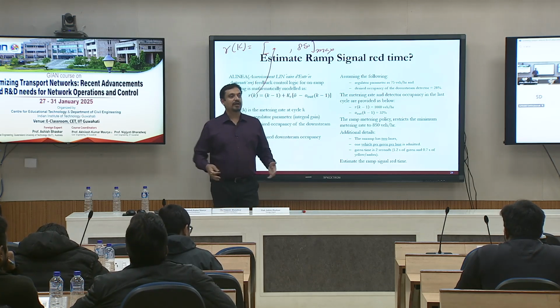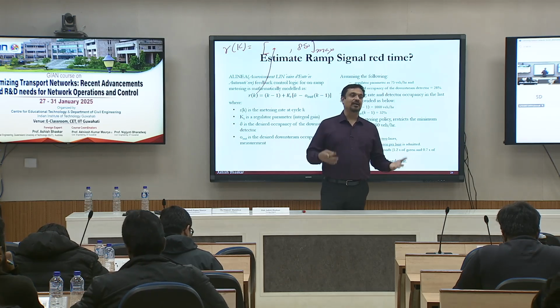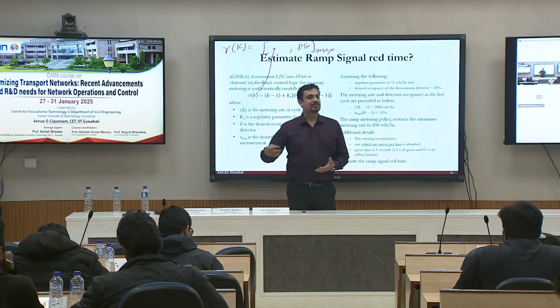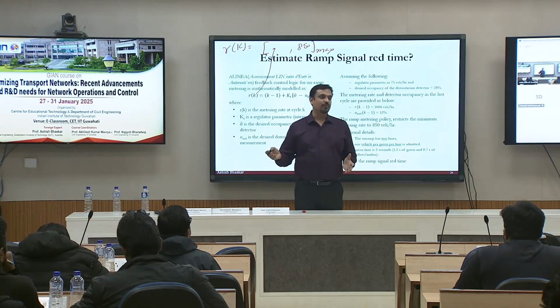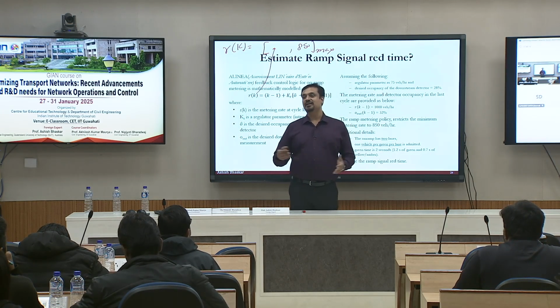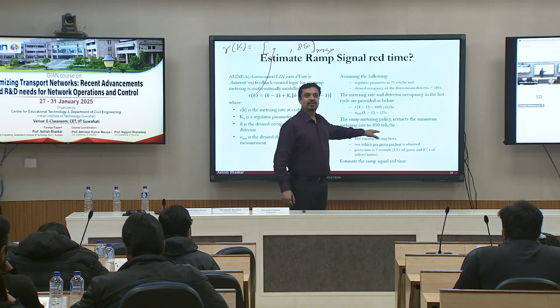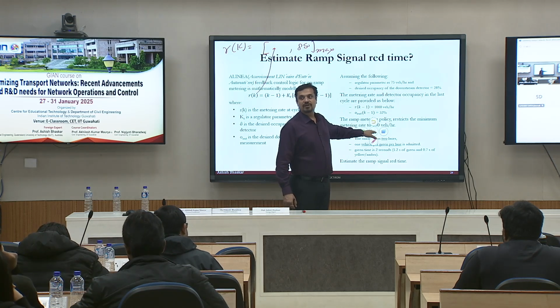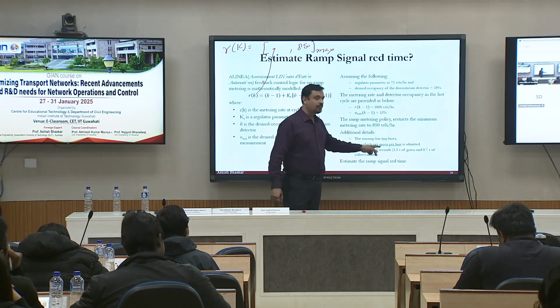That's what they specify, for the site. So this is totally an engineer's judgment. There's a minimum I'm going to specify, and it is that much. Imagine you don't want to have a 3 or 4 minute green time or dead time, right? If you put 850, what is the headway in this case? 4.23 is the headway, but you have two lanes.